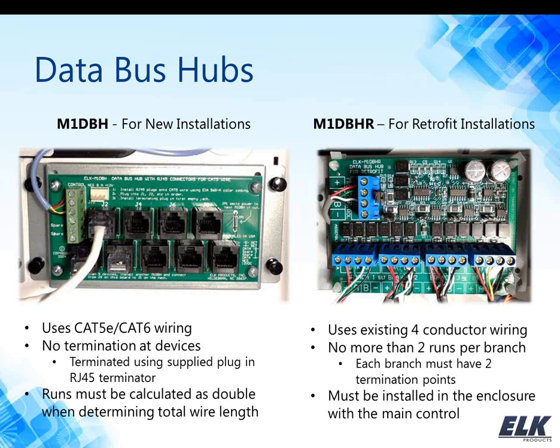Now, a little side note here, the M1DBH-R needs to be close to the control panel. You can't mount it far away, like on the other side of the house or anywhere else. It needs to be relatively close to the M1 to actually get it to work properly.